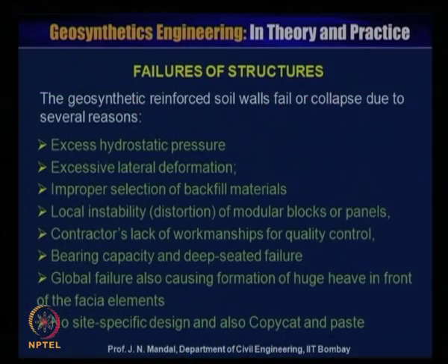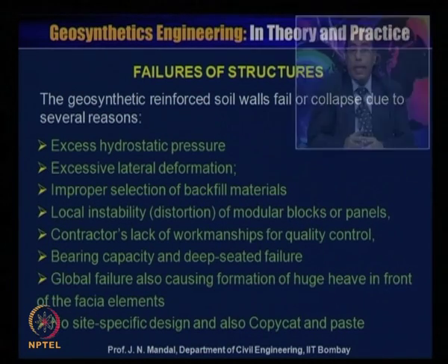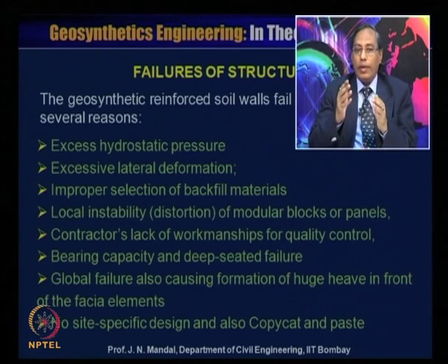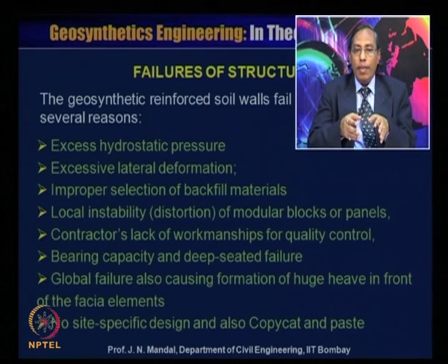And also you have to check bearing capacity and deep-seated failure. So, you check the bearing capacity, you require proper soil exploration in detail and check what will be the bearing capacity of the soil in that locality. If it satisfies whatever you require, then it is okay. If it is not, then you need to improve the soil. I mentioned different types of systems to improve the soil, and you check the bearing capacity.